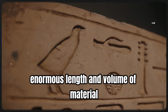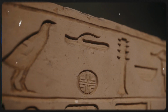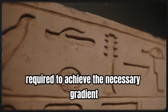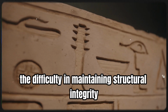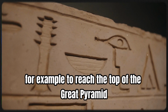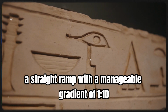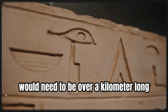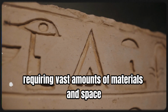Challenges: enormous length and volume of material required to achieve the necessary gradient. The difficulty in maintaining structural integrity over such a long distance. For example, to reach the top of the Great Pyramid, a straight ramp with a manageable gradient of 1 in 10 would need to be over a kilometer long, requiring vast amounts of materials and space.